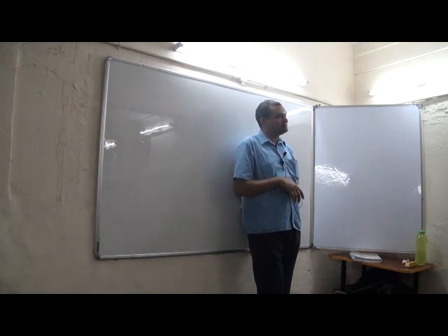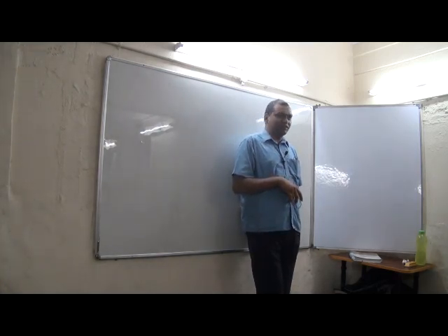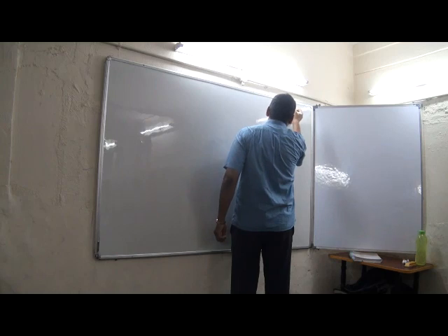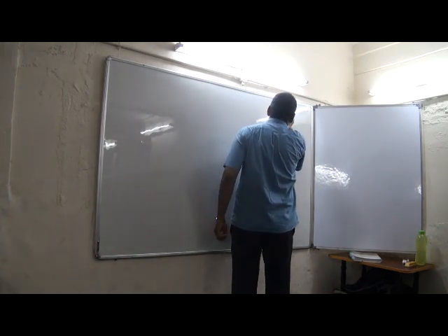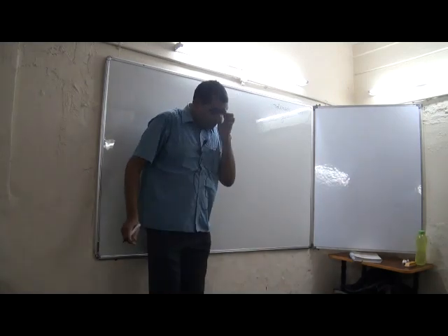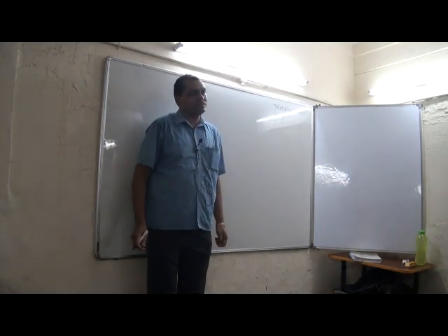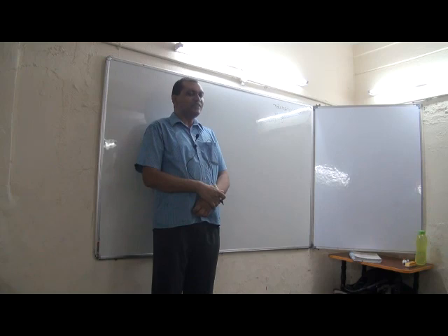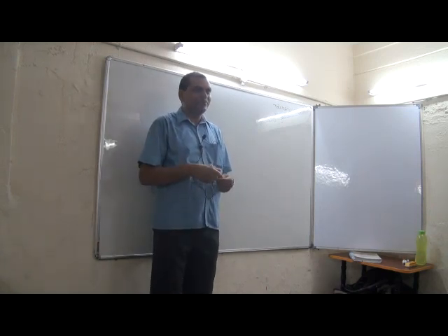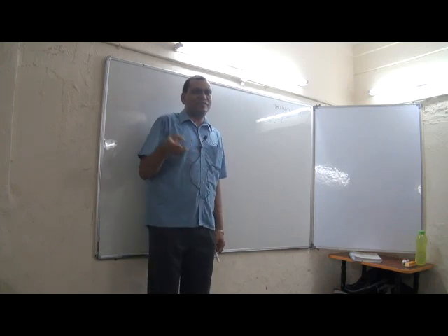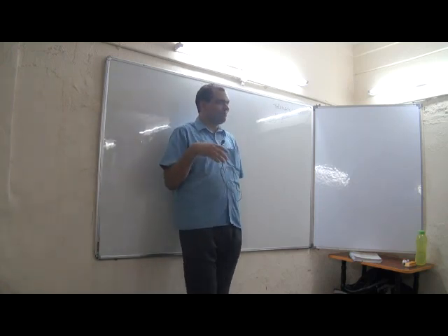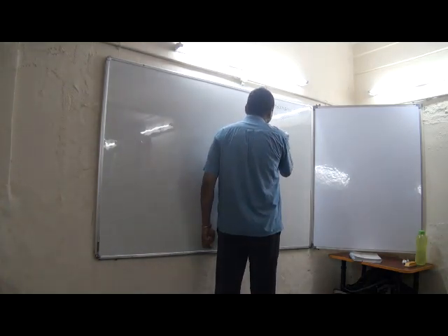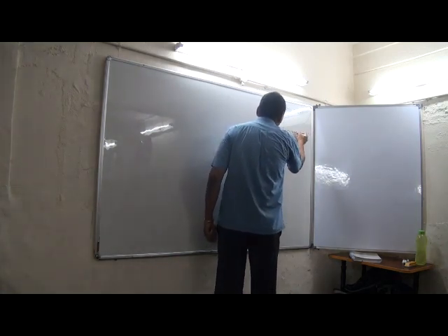Everywhere there will be tolerances. So there will be tolerances on the gauges also. So tolerance on gauge is called a necessary evil. Why necessary evil? We don't want it, but without tolerances we cannot produce it. So when we have to give tolerance on the gauges, this gauge tolerance we will give as 1/10 of the work tolerance.